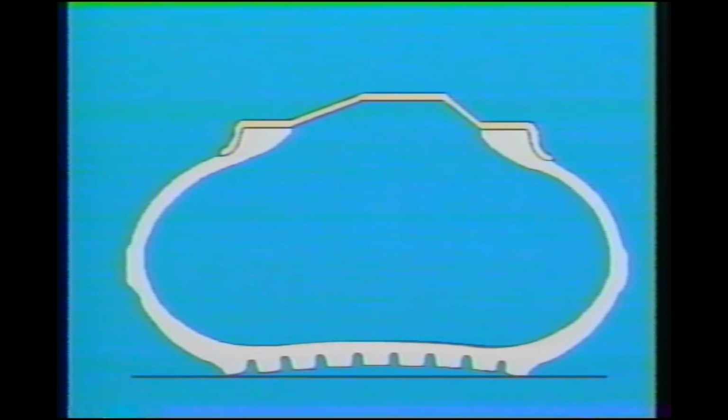The tire must be inflated with enough air to counteract the weight of the vehicle. This will allow the tread to fully contact the road. When the tire is underinflated, the weight of the vehicle pushes on the sidewalls. This causes the center of the tread to buckle, resulting in a loss of traction.